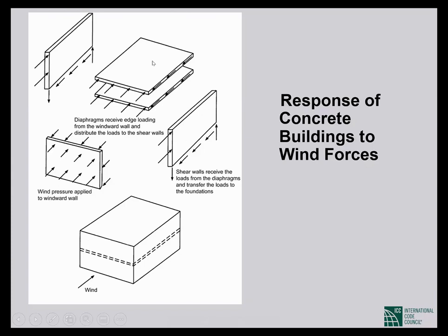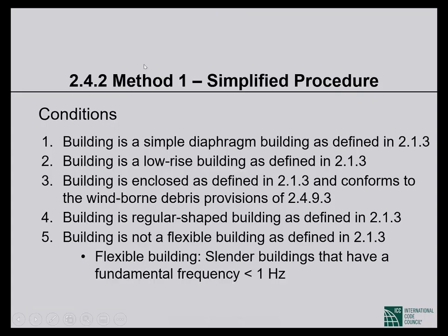When we use the term slab, we are thinking of out-of-plane bending under gravity. When the same slab bends in its own plane under lateral loads, we call it a diaphragm. Okay, so this wall will transfer the wind applied to it to the diaphragms, as you see in the picture. Those diaphragms will develop tension along this edge. I'm sorry.